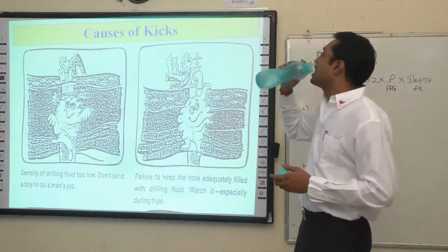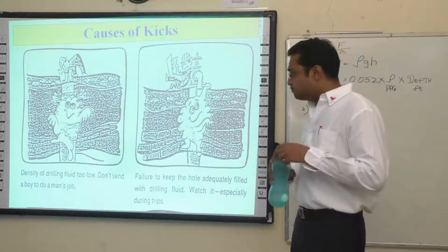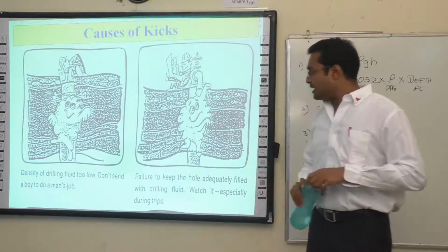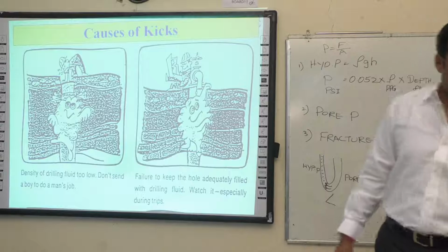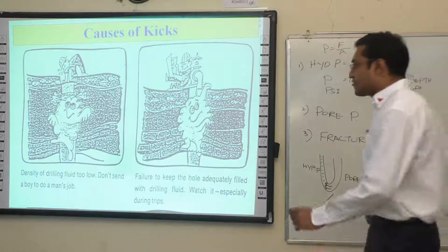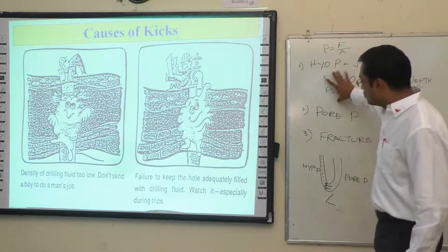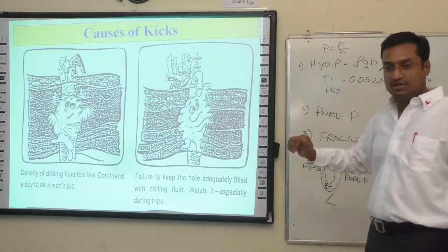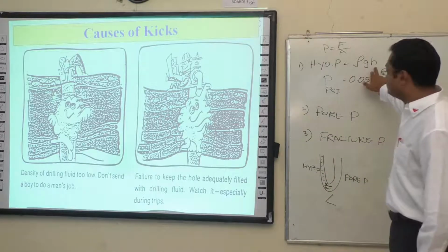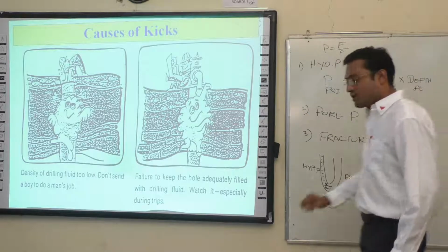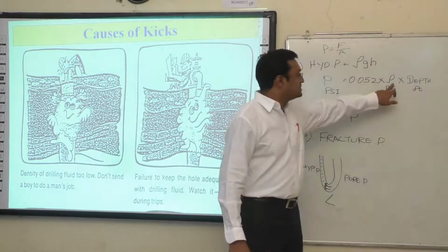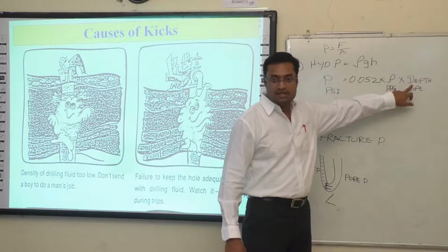Underbalance condition. When the underbalance condition happens, in this formula, the hydrostatic pressure goes less than the pore pressure. So there are some parameters here. The density and the depth.